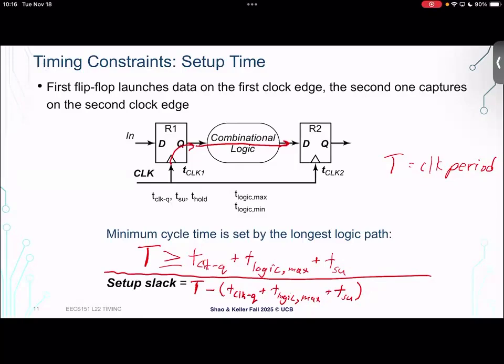Yeah, good question. So for setup, as we alluded to earlier, it's not just doing one pass to optimize the design, it's doing iterative loops, right? If it's on loop number 1 and it finds some paths that are violating the setup time constraint, it'll go back and optimize those paths and try to make them faster. If it's on loop number 25 and it's still stuck, eventually it will give up and just report out to you. We're going to talk in a few minutes about what to do if we're failing, but that's roughly what the tool would do. Okay, any other questions about setup time constraint?